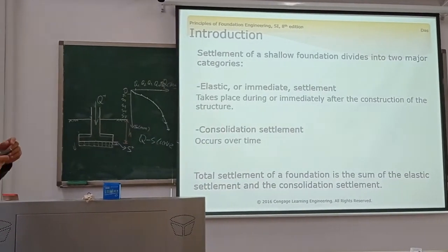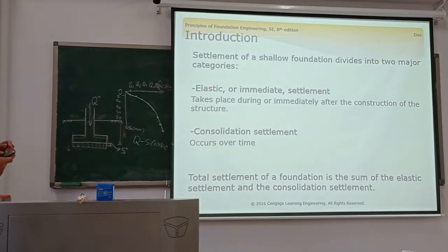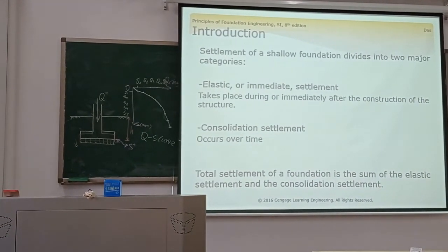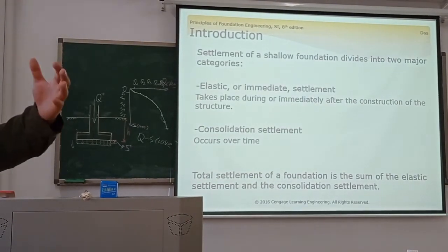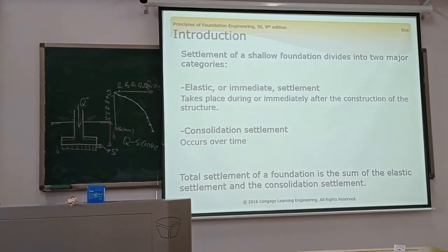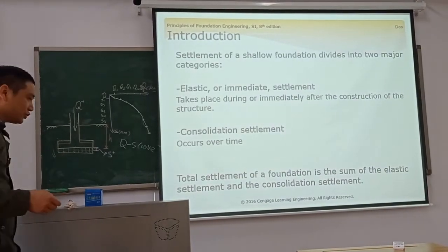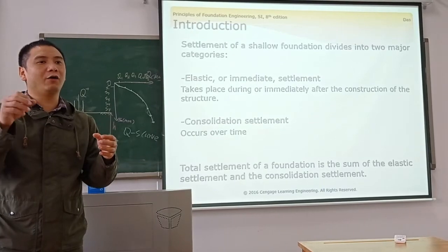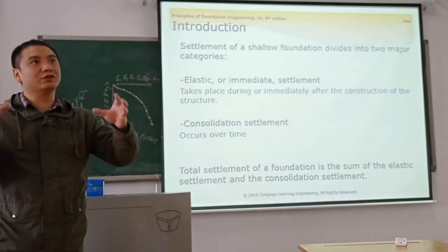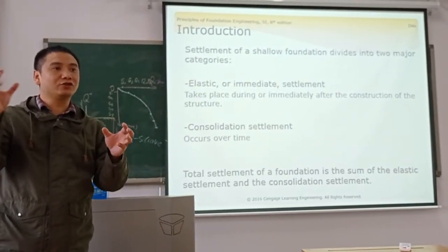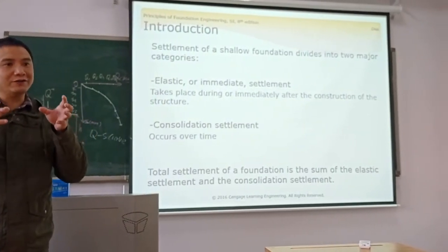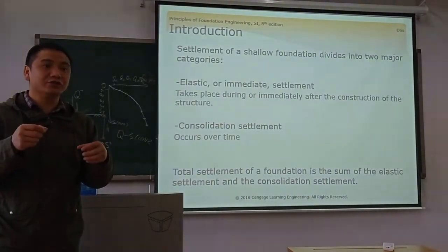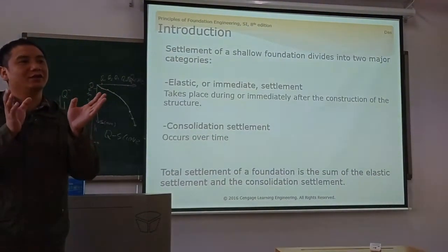Can you have this kind of displacement, like lateral one, horizontal one, for the foundation? Right now it's down, right? Yes, it's down, vertical one. So is it possible to have lateral force? Yes, it's another question. Usually the shallow foundation is not used to support the lateral force or horizontal load. When there is much lateral load, then we use other types of foundation, like the deep foundation, pile foundation, and so on, because the shallow foundation usually does not support much lateral loads.